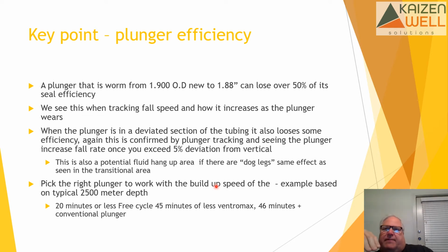So if you're going to drop a conventional plunger, it takes 15 minutes for that plunger to fall from surface to bottom to where your bottom hole spring is. But if your well is building up fast enough and almost becoming stable, let's say in about 20 minutes of flow time, so it snaps up and builds and kind of levels up if you're watching your build up, if it levels off, but you're going to leave the well shut in for an extra 30 minutes, even though you're not building up pressure anymore, it's probably the wrong application to use a conventional.